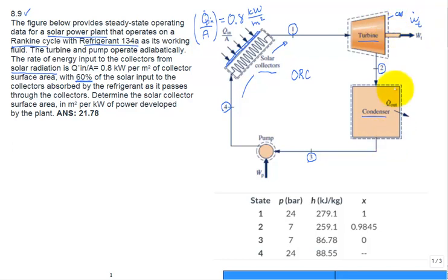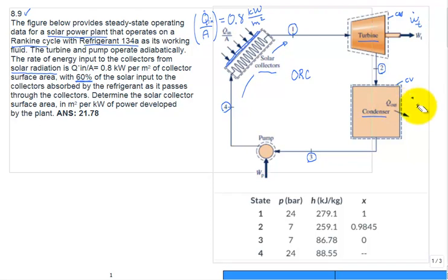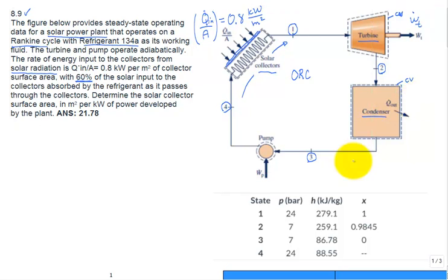But when we come down here, we have a little control volume around the condenser, and they have this symbol Q dot out. Normally if you don't have any out on it, you just say Q dot, that would be positive in. So you're always struggling with a sign problem here to keep these things straight. Here Q dot is shown as positive in the outward direction.